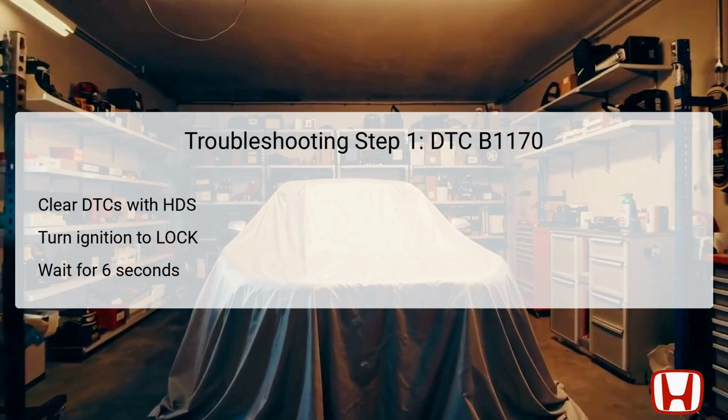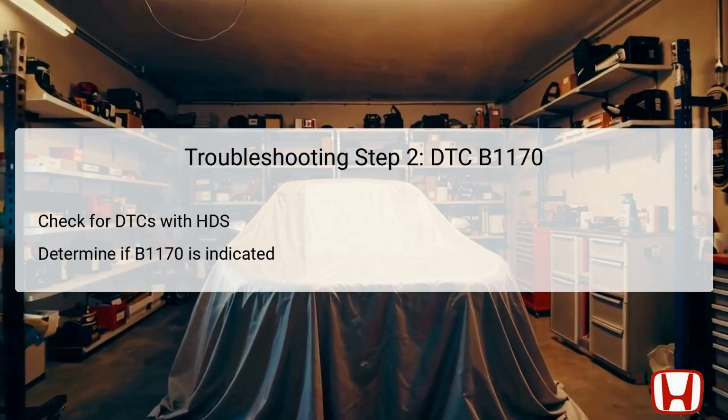In the second step, the technician must check for DTCs again using the HDS after clearing them. This will confirm whether DTC B1170 has reappeared. If the HDS indicates the presence of DTC B1170, this suggests that the communication issue is still ongoing. On the other hand, if DTC B1170 is not indicated, it may suggest an intermittent failure.